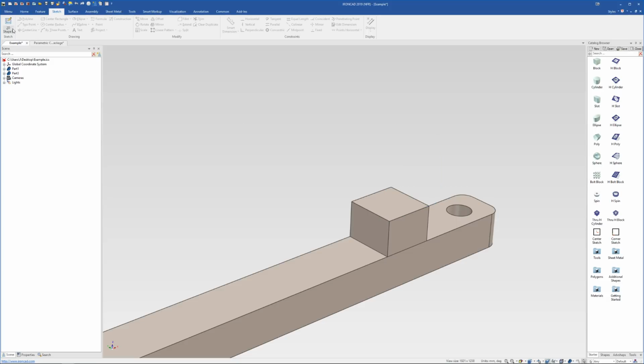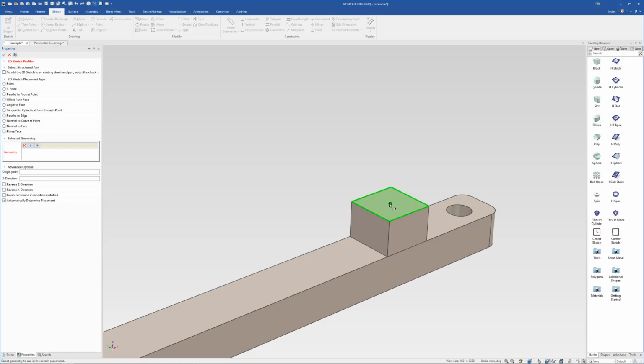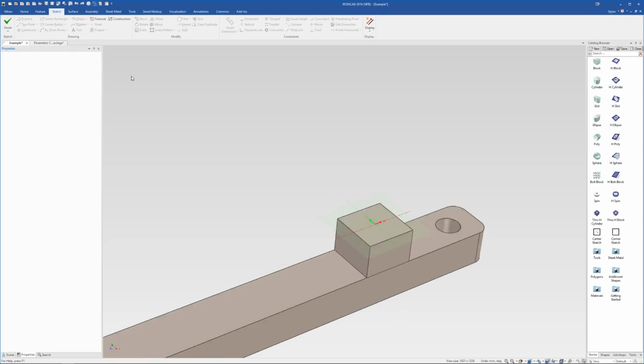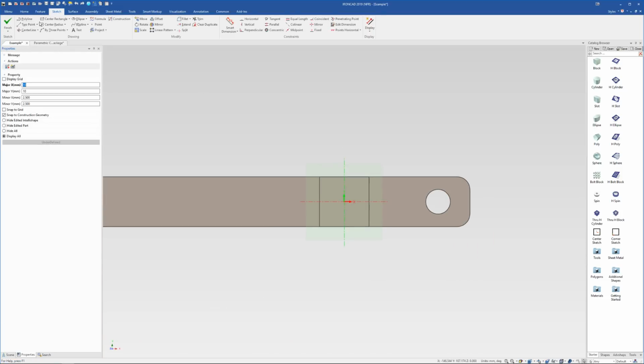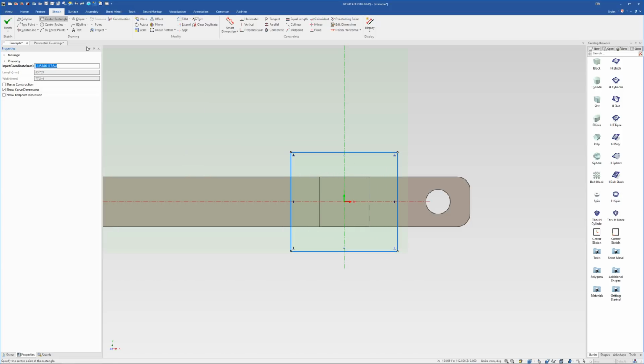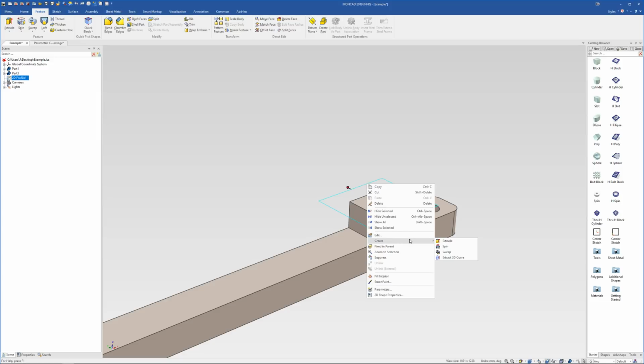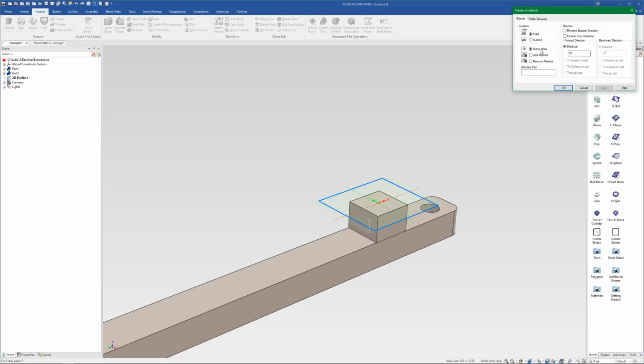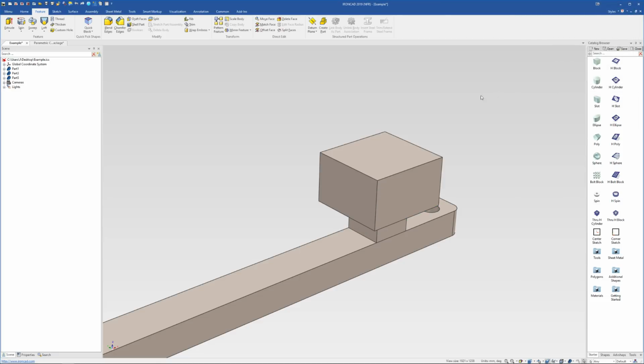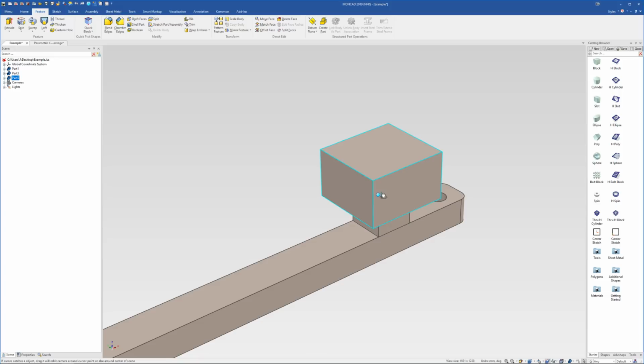But that being said, sometimes you do want to do an extrusion using the standard 2D sketch and extrude command. So when you do that, one tip which I was mentioning in that tips and tricks area is that you can actually convert your shape into an IntelliShape. IronCAD IntelliShapes obviously make it a lot easier and faster to resize things. But if you just do a standard extrude here, let's just right click on this and do create extrude, and we'll make it 50 mil, and we'll do a standalone part. That's good enough. So we've created an extrude there.